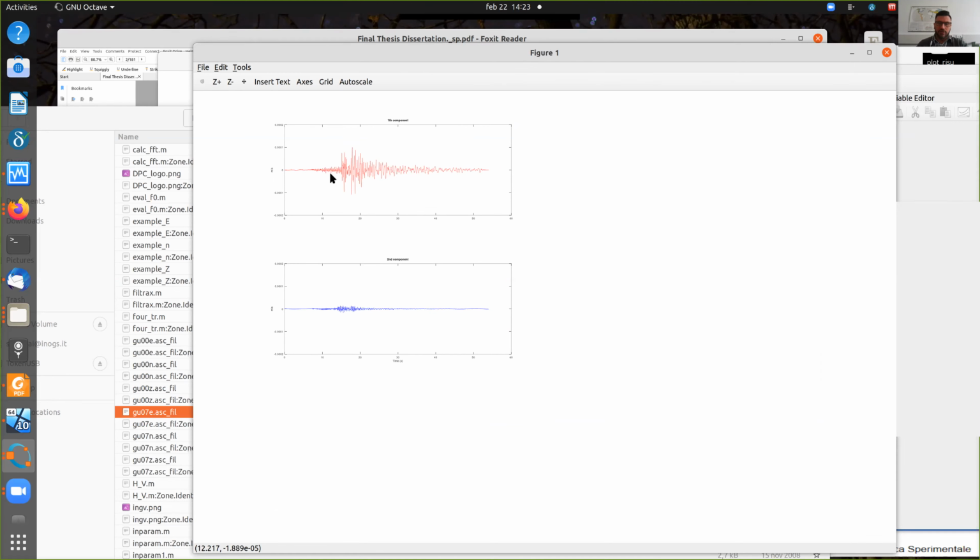If I want to calculate the site response, I know from my bulletin, from my seismological network, that this earthquake is quite far away from my station. So I know that this is a good rock site. I can estimate the site response at this site simply by calculating its Fourier transform, the Fourier transform of this, and taking the ratio. So now I'm selecting a window of signal.